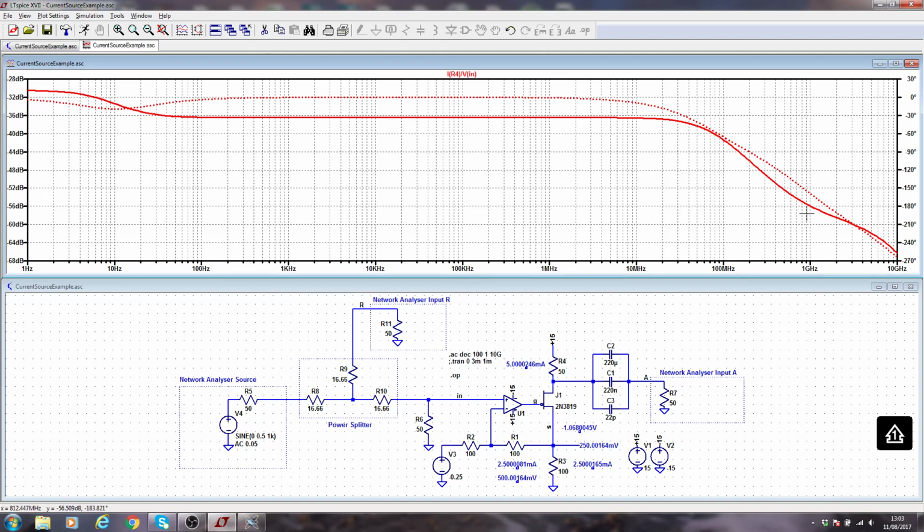That's minus 56. That's at minus 42-ish. So it looks like that's heading for 20 dB per decade, but it then bends back because there's a 0 here. And then it looks like another pole, because the old phase is going down for all the poles. You can see the phase starts to go back up a little bit just here. Not really up, but it starts to turn. It's not going quite steeply down. But that's by the by.